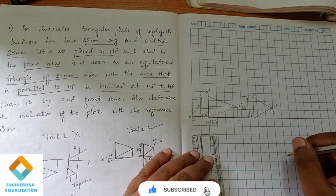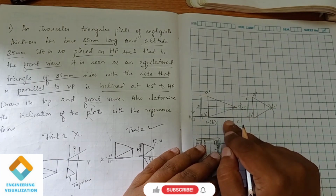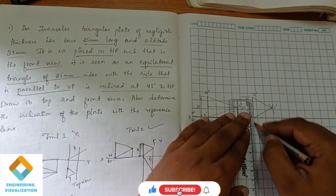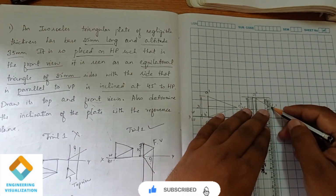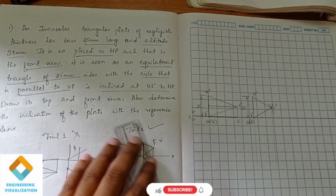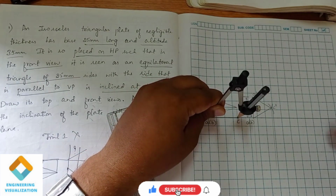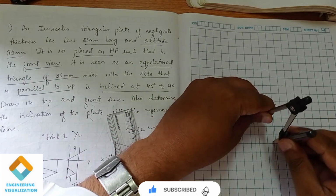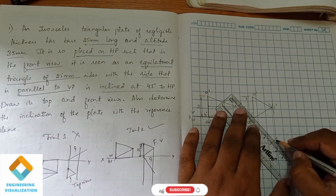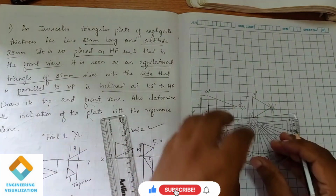So this is an equilateral triangle, but we need to find out how much inclination we get here, how much tilt we have to give this isosceles triangle such that we get an equilateral triangle here. For that I'll just draw a projection line here. Here at this point I will take a reference point, A dash B dash, then measuring this line A to C, we are measuring this length A to C, I am going to cut the arc. So now we can find out how much angle of inclination it is.